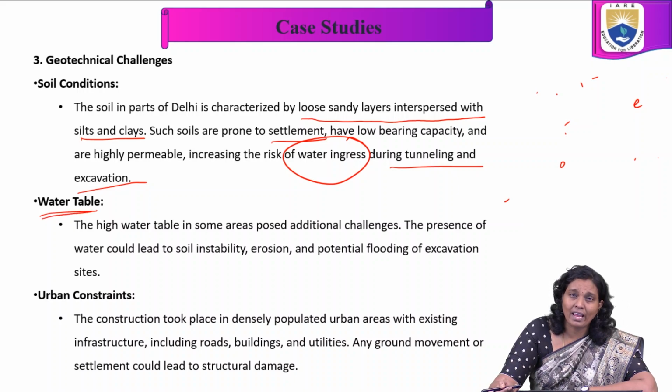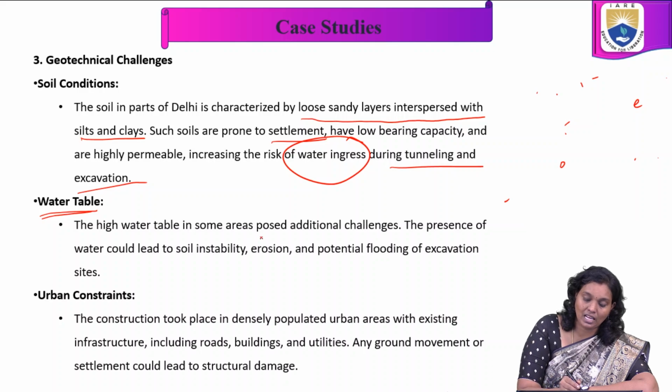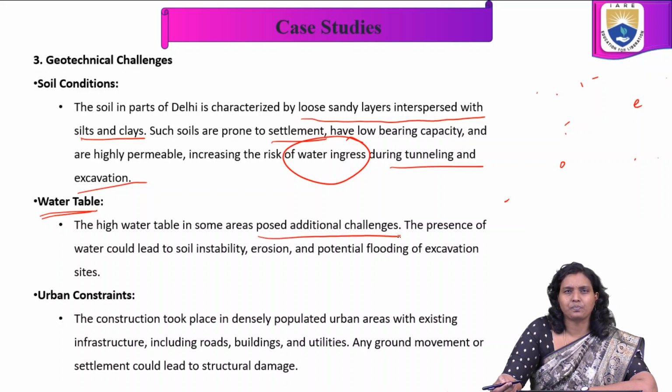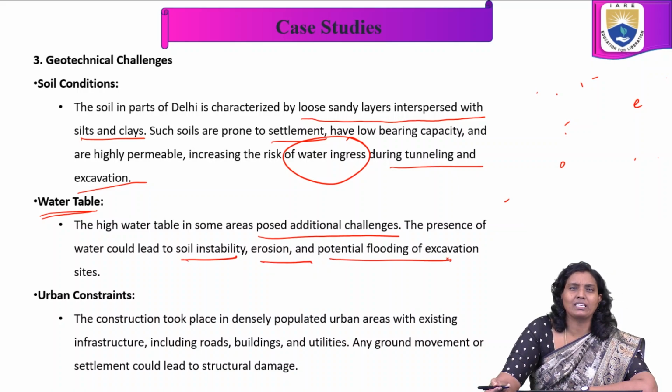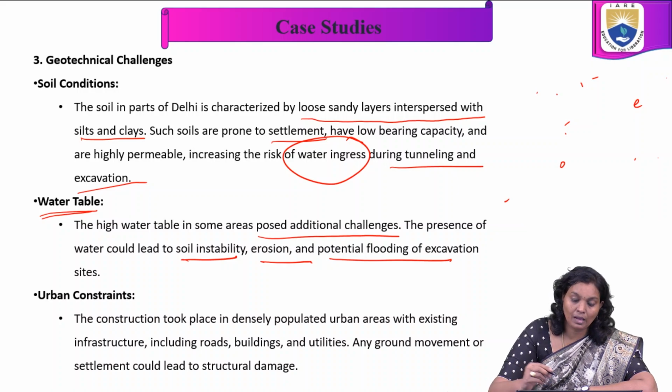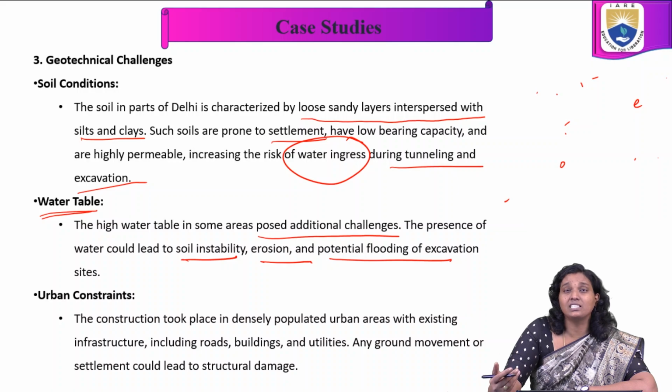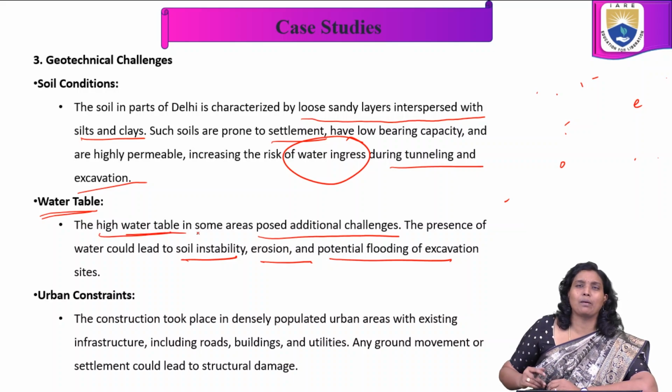The water table depth is one more challenge we are going to face in this particular construction work. So a high water table in some areas poses additional challenges. The presence of water could lead to soil instability, erosion, and potential flooding of excavation sites. So these are the challenges: soil erosion, instability, and whenever we are doing excavation, potential flooding will happen on these sites. These are the challenges we face because of the high water table in some areas.